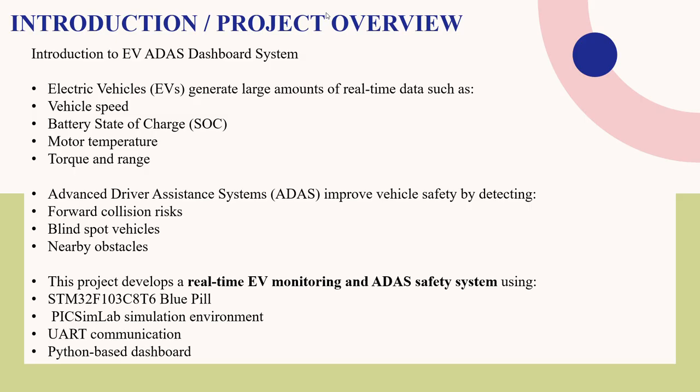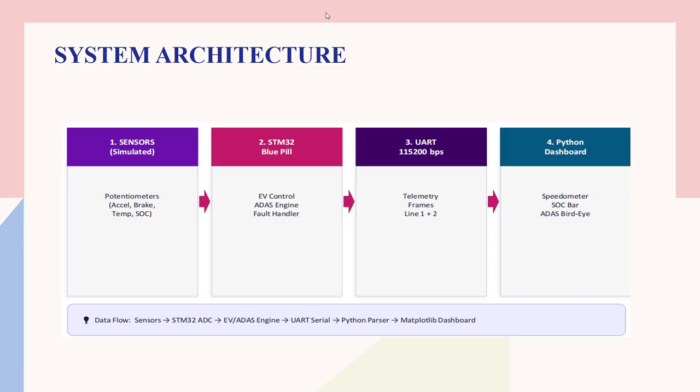Next, ADAS. ADAS means Advanced Driver Assistance Systems. This improves vehicle safety by detecting collision risks, blind spot vehicles, and nearby obstacles. This project develops a real-time EV monitoring and ADAS safety system using STM32 F103C8 Blue Pill, PICSimLab simulation environment, UART communication, and a Python based dashboard.